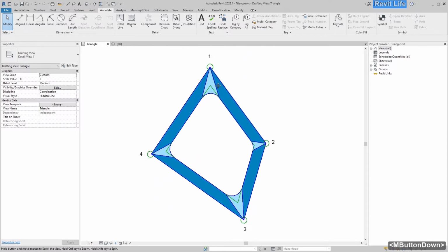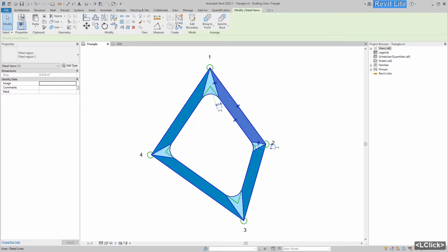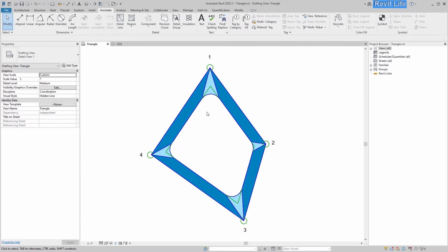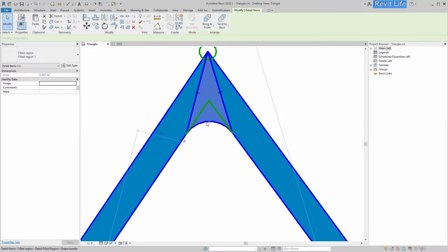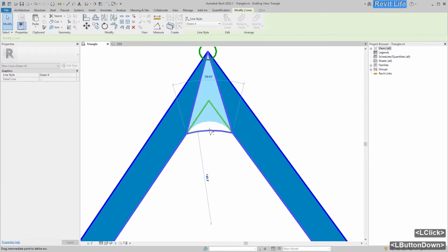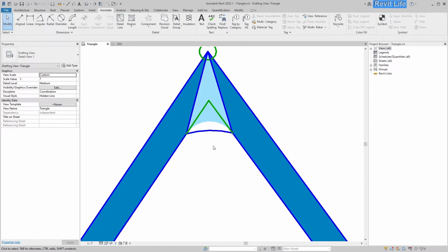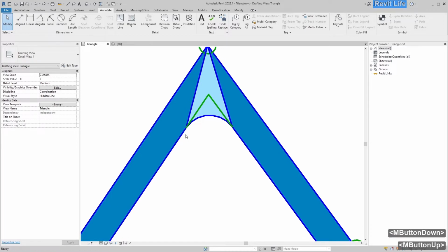So this next drawing represents surfaces that are going to be used, and 4 adaptive points that are going to control our family. So we will divide our top into 1, 2, 3, 4, 5, 6, 7, and 8 main surfaces. And we need reference lines to make those surfaces. And the most difficult one is this reference line that represents a fillet arc in the corner of this family. So this arc needs to be tangent to those offset lines in the middle. And we need to calculate the length of this arc's radius.